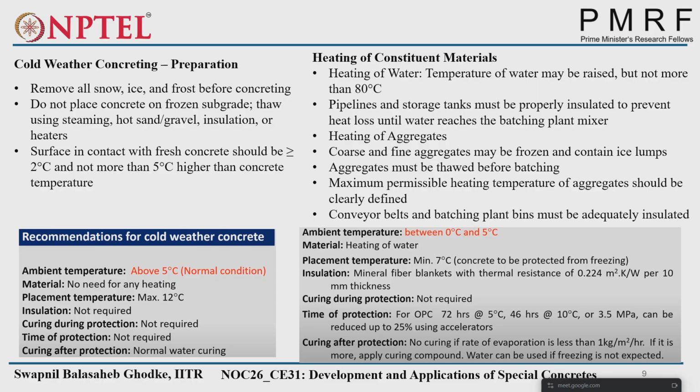And for curing after protection, no curing is needed if the rate of evaporation is low. If the rate of evaporation of concrete is 1 kg per square meter per hour or greater, then curing protection is required because the water evaporation is very high. But if it is less than that, no curing protection is required.